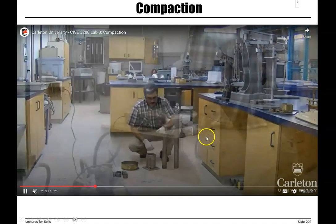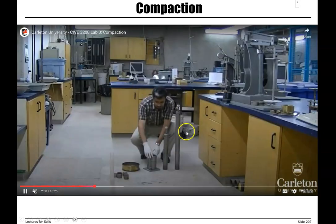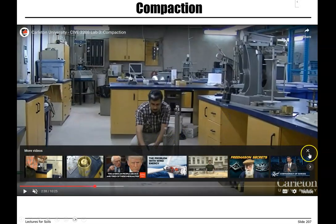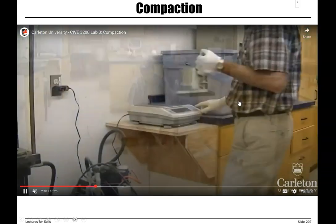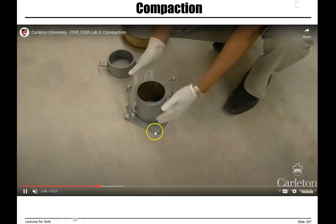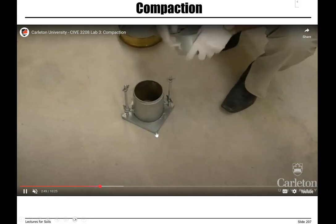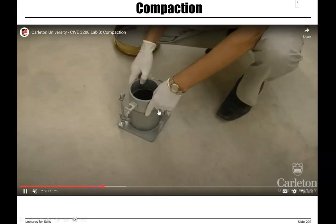As you can see, we have 2 hammers. The smaller hammer is for the standard Proctor test, and the larger one is for modified Proctor test. This is the mold we need to use, and these are small cans so that we can find the moisture content of our soil. So you need to measure weight of mold with the base plate when it's empty, and don't add the extension at the beginning.